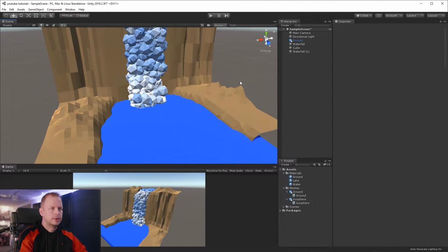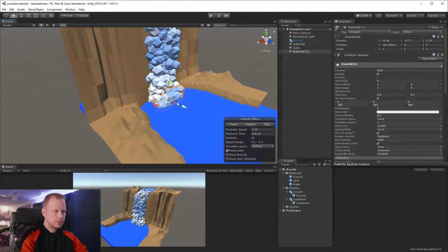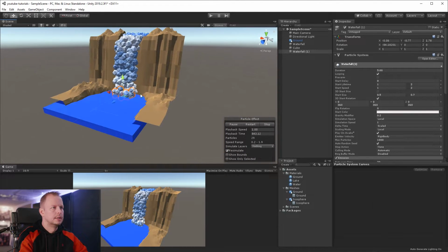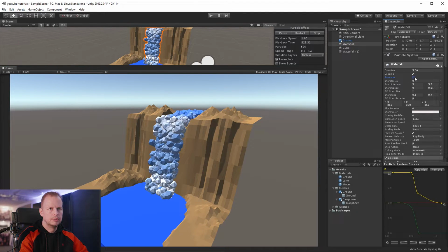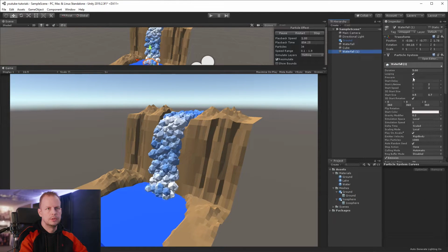So there we go. And finally, you can play around with this a lot more, and I'd recommend changing the water shader to a proper shader, that you can find in the standard assets. I think there are some examples of water that will create some ripples around this edge there. Oh yeah, one final thing, and that's for the waterfall here. You want to set it to pre-warm, so you don't have to wait for the initial water particles to come, and same for the second one.